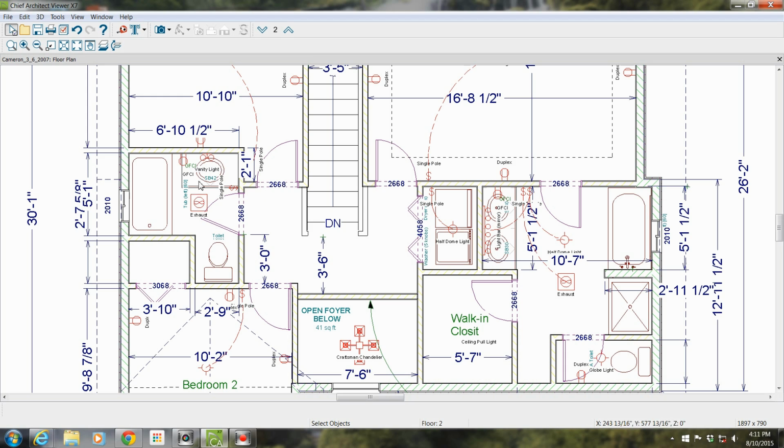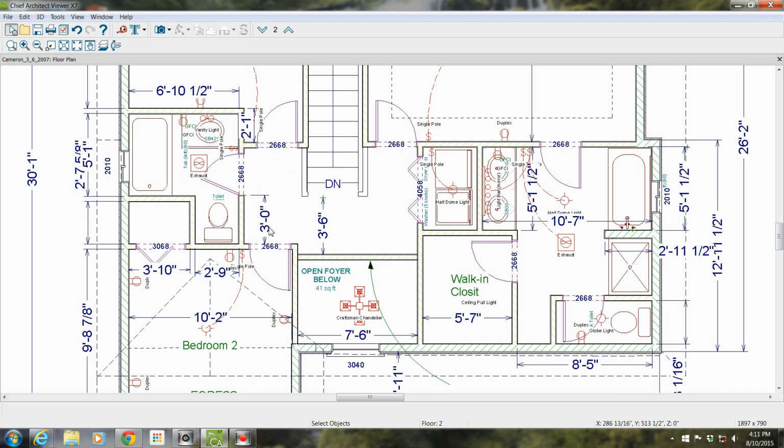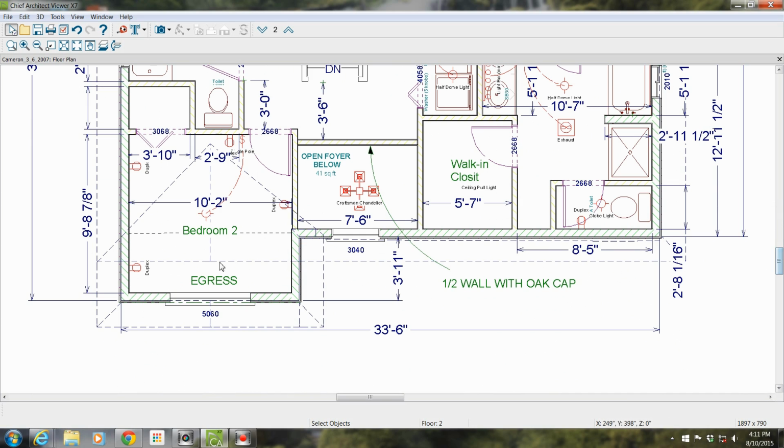And here, bedroom again, vanity, sink base 24, tub, exhaust fan, toilet again. That's the hall bath. And we're going to come into the second bedroom, and these dotted lines here are the roof lines, and this is going to be a small gable over this, so that shows you how that roof line lays over this. So you could do something with a little vault in here. If you're looking at this roof line, instead of having a flat ceiling here, you could do a little vault in this room, which would be nice.